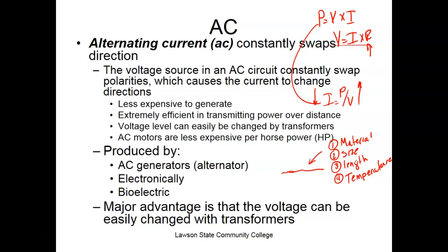If you're lucky, it's got a big box out there somewhere, usually on the corner, where they have these transformers in it, which usually serves about 3 or 4 houses in a block. And what are the 2 voltages we use in our house primarily? Yeah, 240 and 120. That's what we call it, plus or minus 10%. They try to get it to you as best they can.